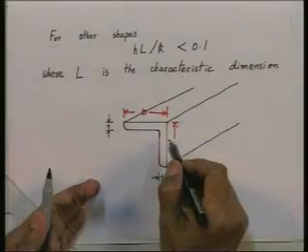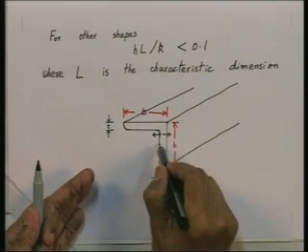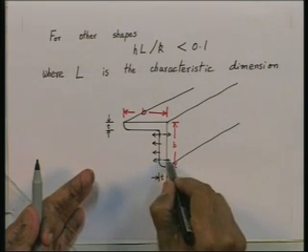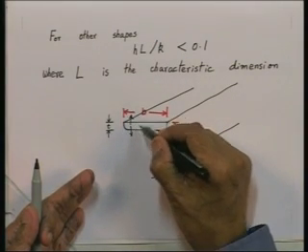What will I take as the characteristic dimension? If this is going through some transient heat conduction process and I want to know whether to neglect internal temperature gradients or not, well, ask yourself now, how will heat flow if this angle iron is going through a cooling process? You will see that the heat from this angle iron will primarily flow like this. These are the dominating phases through which heat is flowing, isn't it? If it is undergoing an unsteady state, like this or like this.